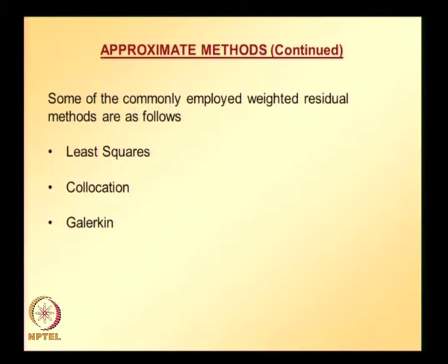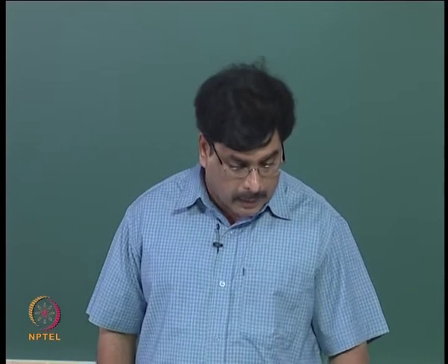into three types. Some of the commonly employed weighted residual methods are least square weighted residual methods, collocation weighted residual methods, and Galerkin weighted residual methods. We looked at length at each of these methods, and the details involved in getting the approximate solution, starting with a quadratic trial solution in the last class. So, just to summarize once again,